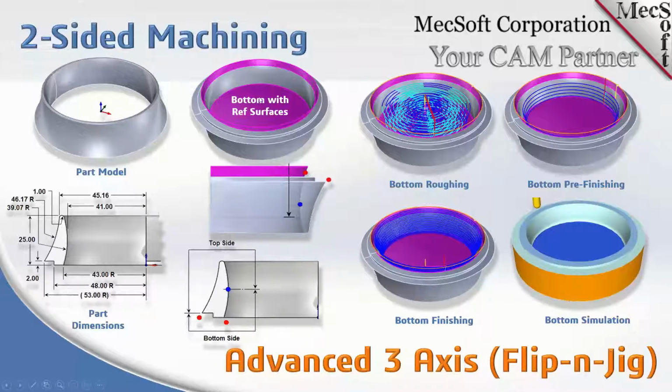If you look in the second column, in many cases also the purple or magenta surfaces. In this particular example, we have critical edges that we don't want to lose the definition of. And those are the sharp corners on the bottom of the part, both on the outside and on the inside. So what we did is you add a surface. The flat surface here is, again, a place for the tool to land on.